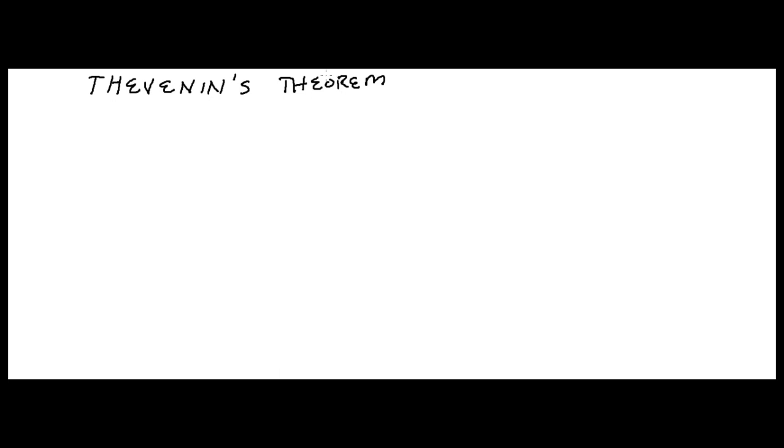this is a very useful theorem, and it's going to be useful to you in your study of electronics because it's going to enable you to simplify complex circuits. Alright? So, Thevenin's theorem provides a method for simplifying a circuit into a standard equivalent form with respect to two output terminals. This theorem can be used to simplify the analysis of many complex circuits.